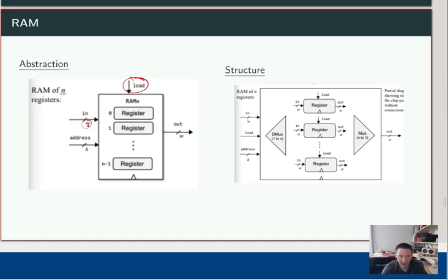If you're stuck trying to think how to implement this, that's all shown on the right. Same kind of interface: in, address, load, and out. Internally, what we want to do is use a demux to take our signals, translate them, and connect them to the many different chips we have. Then we want to be able to load a value onto one of the specific registers that the user is asking for, load it somewhere up in this big array of chips and RAM storage registers, and then pass that along to the output.